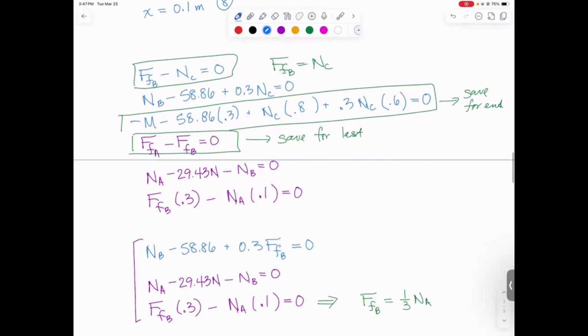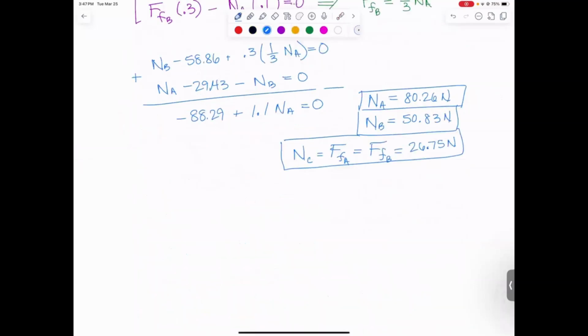And then we can solve for a couple of other things, but as far back as we really need to go is just to get the moment. Plugging into that moment equation, you get that the moment to cause this motion to occur is 8.56 Newton meters. Now this might be the right answer or it might not. So what we want to do is we had 2 other possible motions. I want to check them both. So let's check number 2.